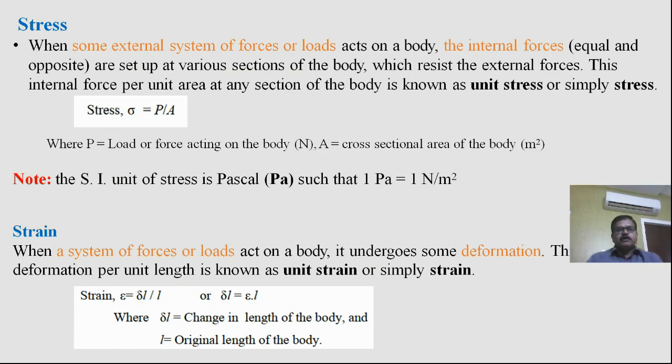For the design of a machine element, we should understand the types of stresses the member is going to experience and the maximum stress induced in the member due to the application of forces in the axial direction, whether it is tensile or compressive, or in the lateral direction, the shear, or the lateral direction which results in bending stress, or the member is subjected to a twisting moment, that is torsion.